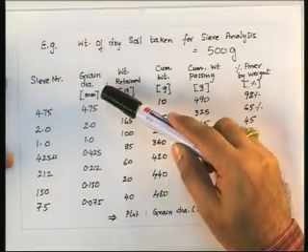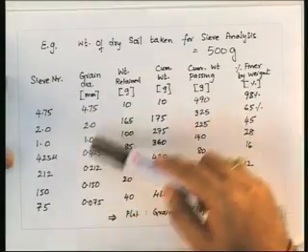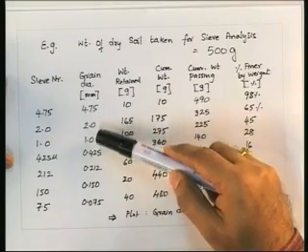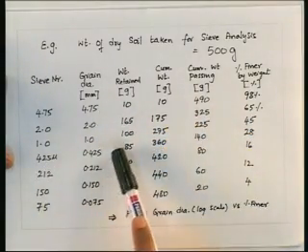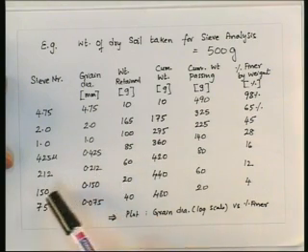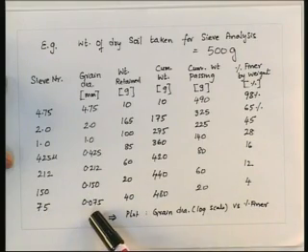Let us assume the grain diameters are equivalent to the sieve sizes, in the form of 4.75, 2 and 1 up to the 1 mm sieve. Then the 425 micron sieve is 0.425 mm, 212 represents a grain diameter of 0.212 mm, 150 is 0.15 mm and 75 micron is 0.075 mm.